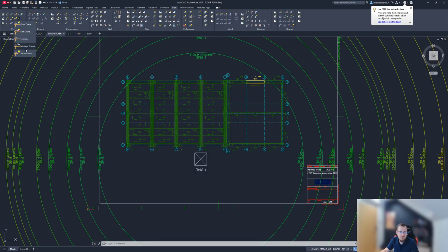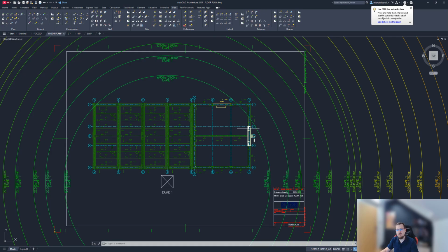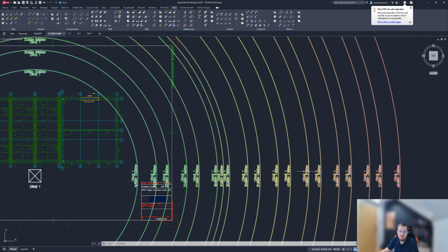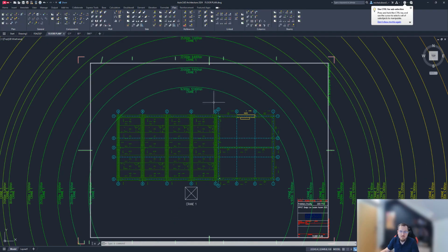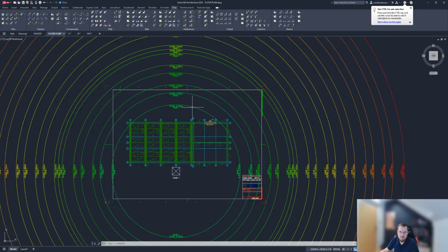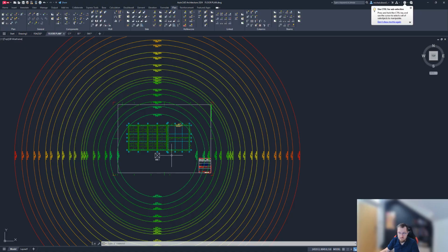Of course, you can turn that off, and if you want, you can do a crane check in Project Manager. But within Impact Design, once you place the elements, if, for example, you place an element of a certain mass at a radius that doesn't allow for that, it will pop up with a warning and the element will be immediately marked red. Even if its size is okay in terms of the production capacity, it will still not be accepted.